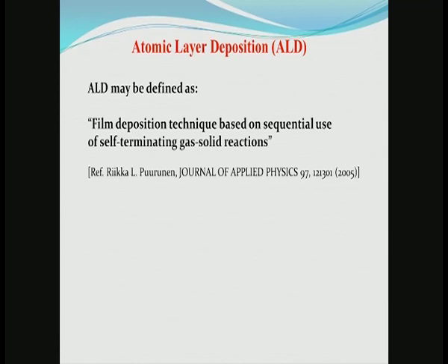What is ALD? ALD may be defined as a film deposition technique based on the sequential use of self-terminating gas-solid reactions. So, the operative thing is the sequential use of self-terminating gas-solid reactions. As I said, in CVD there is a continuous flow of all the reactants involved, whereas in ALD by contrast there is a sequential flow, or pulsing, of reactants into the deposition chamber.